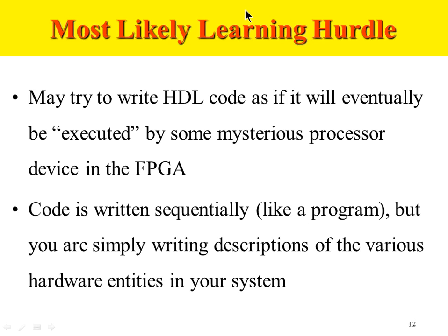So there are certain learning hurdles that you might face. What are some of the hurdles? You may try to write HDL code as if it will eventually be executed by some processor. This is coming from a software background, right? When you write a software program, you compile it, you link it, and you generate a hex code which will get implemented on a processor somewhere. In embedded systems, it will execute those instructions on a processor.